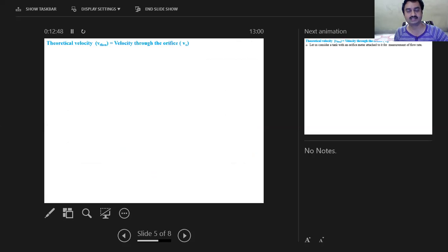Fine. So let's discuss the theoretical velocity first. That is the velocity through orifice. As I said, theoretical term indicates the velocity through the orifice, and the actual indicates the velocity through the vena contracta. So theoretical velocity first of all represented by V subscript O. Okay, fine. So let's try to find out what is the velocity of the streamline at the orifice.